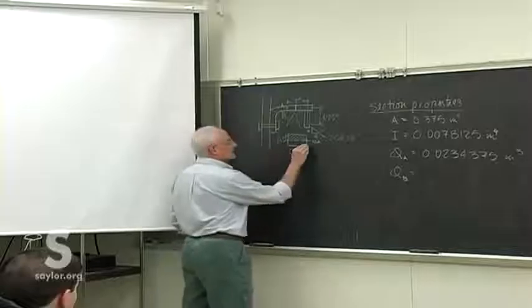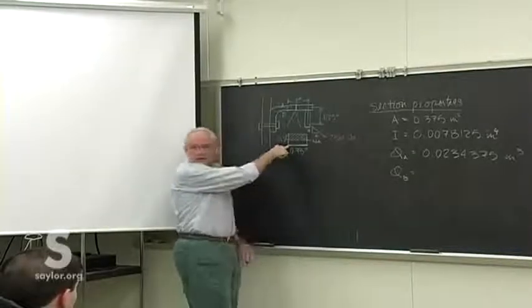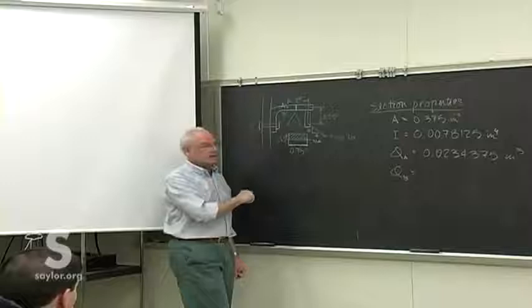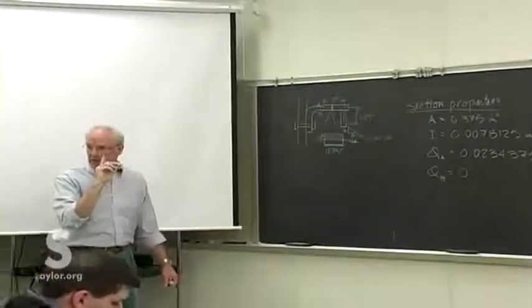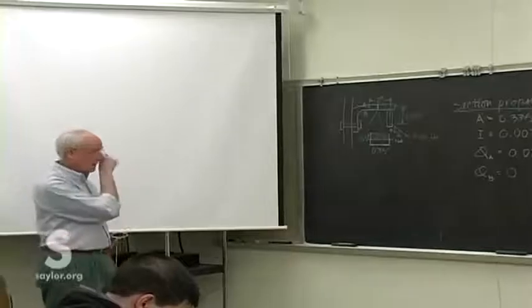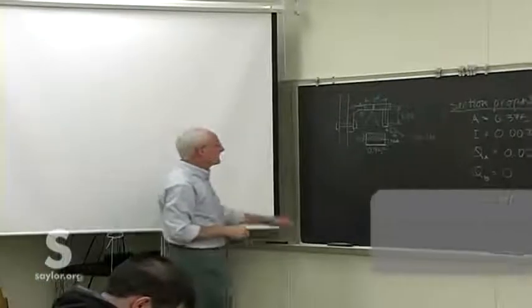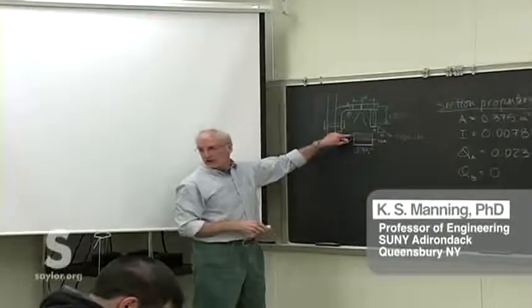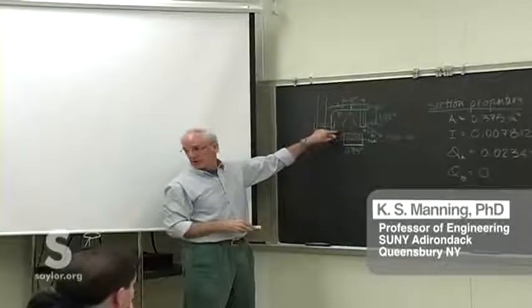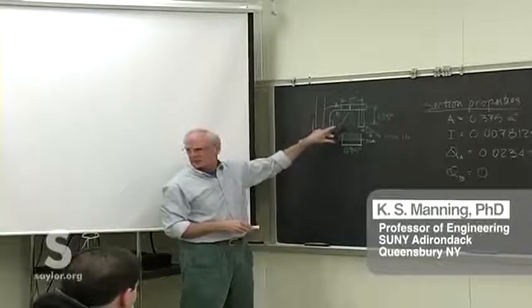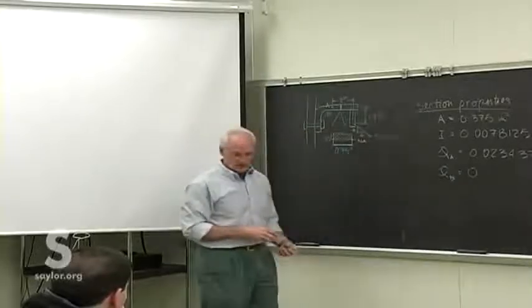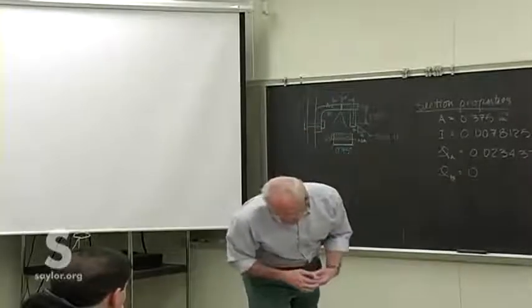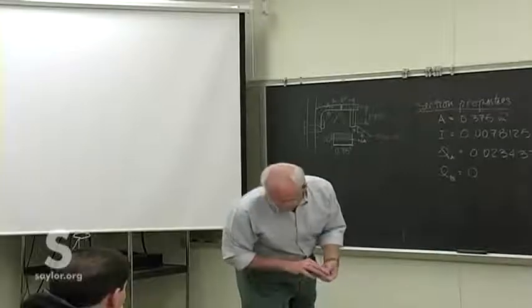And there is no area beyond the neutral axis. We are at the extreme point, so that is 0 for point B, because it is on the outermost bit of material. Don't think that we always do the area above the neutral axis, because that implies that this has something to do with gravity itself, which it doesn't. It has to do with where the forces are and where the points of interest are that we're concerned with.